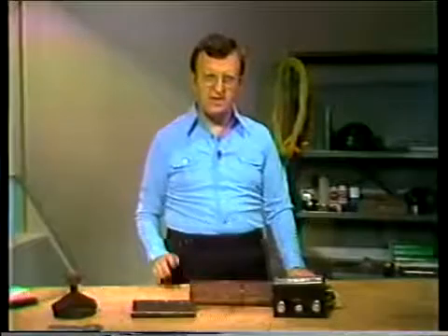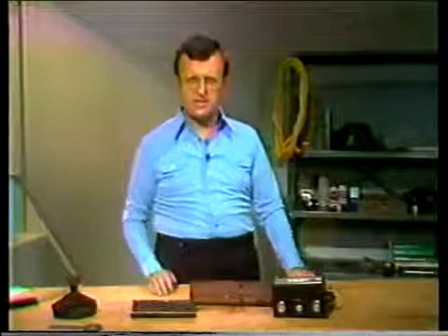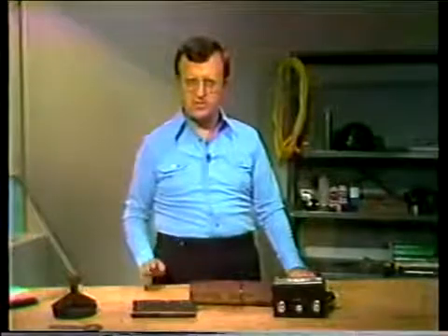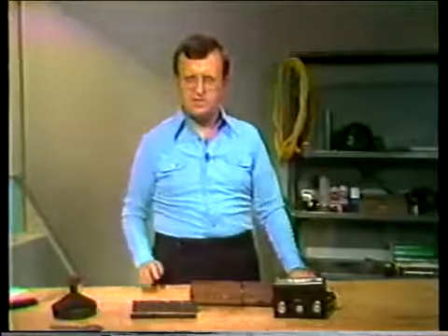Sludge, on the other hand, is a normally soft deposit and rarely sticks to tube or header surfaces. Sludge deposits are heavier than water and tend to accumulate in the tube ends and in the lower drums and headers. If they stay there for a long time, they may get baked onto the inner surfaces. Baked-on sludge can be a major cause of tube failure.